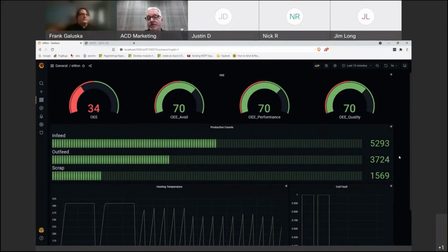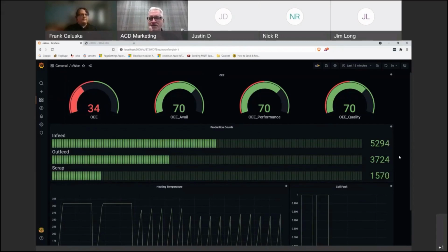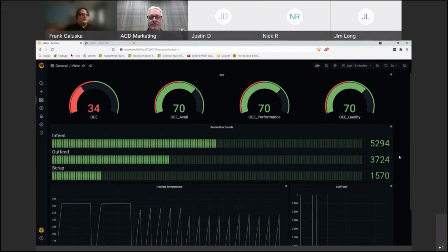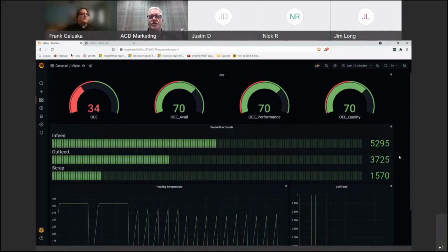That's a good point. That's one of the things that makes using products like the Ewon, where it can push the data out to the cloud, much better. For any firewalls that might be around, you don't need to worry about poking holes, opening ports, or setting rules on those ports for incoming data. It's just outbound only. Yeah.